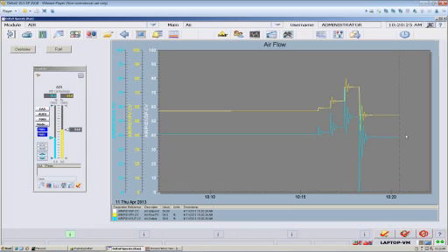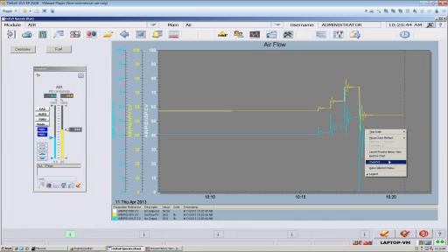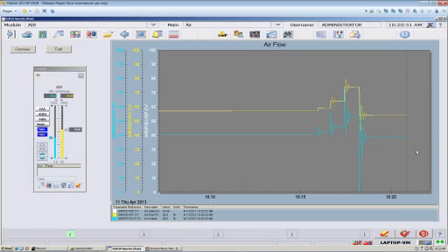I'm going to do something here that I would not do in a real plant, and that is I'm going to make a single bump and calculate tuning parameters from that. I just want to show you how easy the math can be. Before I do, let me zoom in so we can get a finer view of what's going on here. Instead of a 15-minute picture looking at the whole 100% span, let's zoom in.